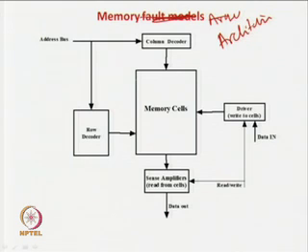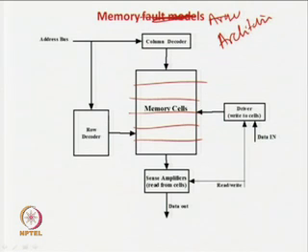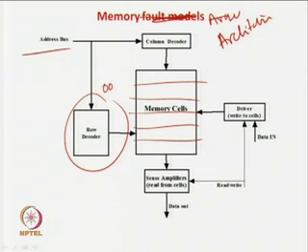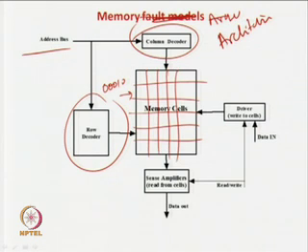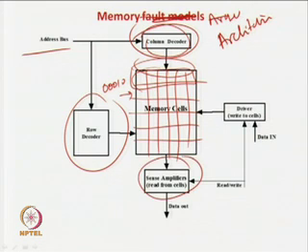It is a standard memory, and you can find it in any book. A memory will have cells. This is a row decoder. You give an address, say 00010, so the second memory location will be accessed. Then you have the column decoder. The memory also has columns, so which part of your data will you access? Generally, you can access the whole word, or you can also access a part of it. The column decoder tells which part of the column you have to decode, and there are sense amplifiers, which are analog circuits that take the data out from the required part.